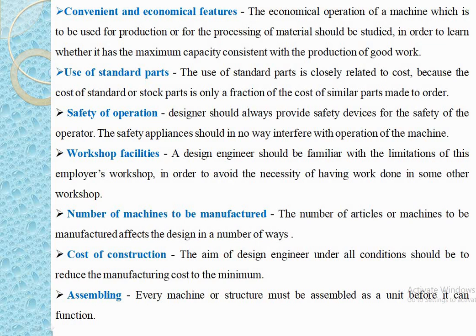If parts are to be changed for different products or replaced on account of wear or breakage, easy access should be provided, and the necessity of removing other parts to accomplish this should be avoided if possible. That means the usual replacement of the parts should be avoided, and the starting, controlling and stopping levers should be located on the basis of conventional handling.